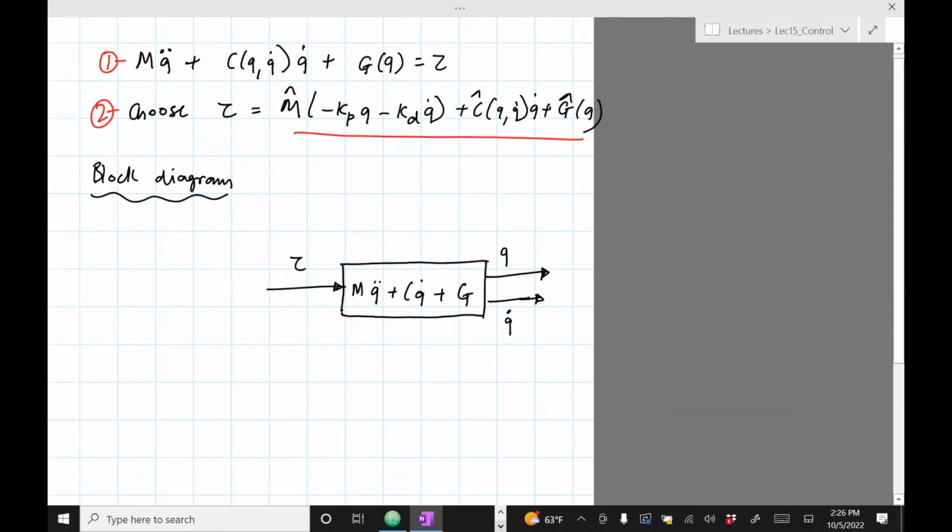And now this is just equation number one. Now equation number two has to be also shown in the block diagram. So I need to now connect the dots. I need to take feedback. I need to take Q dot, multiply with the right quantities over there, and that gives me the torque. So you can see that the torque is composed of a summation of a few things.